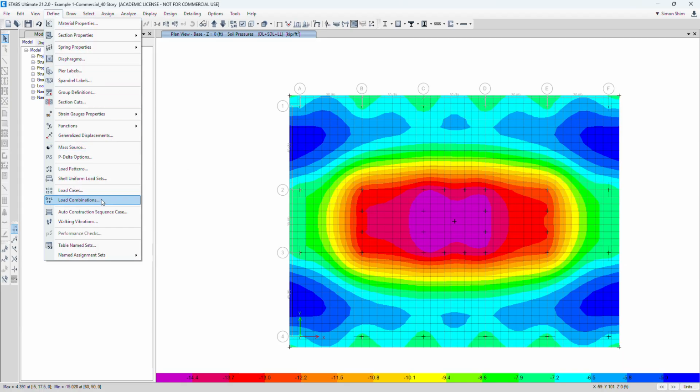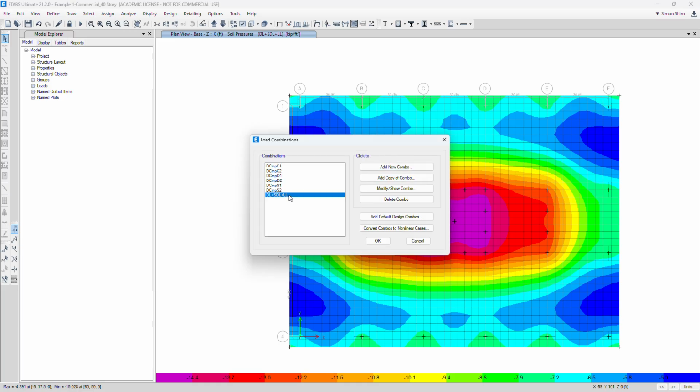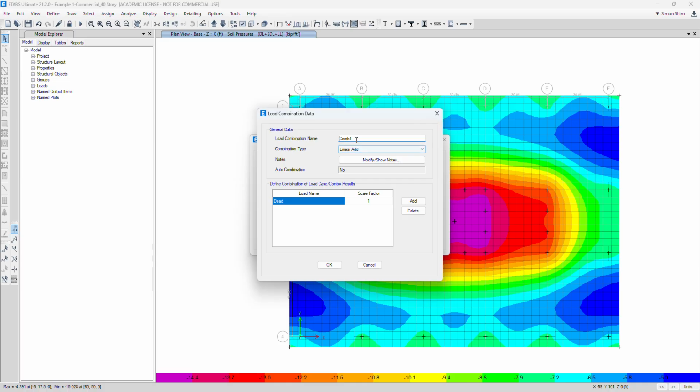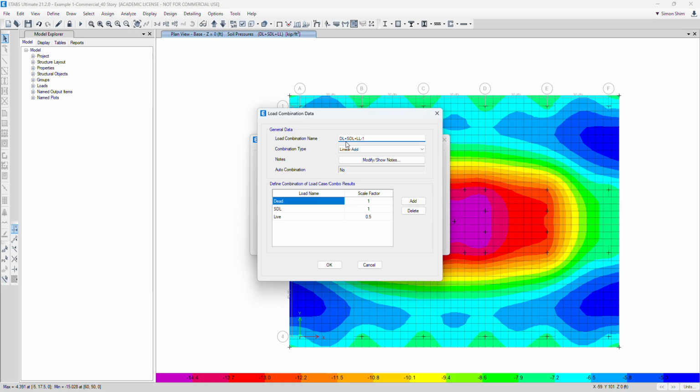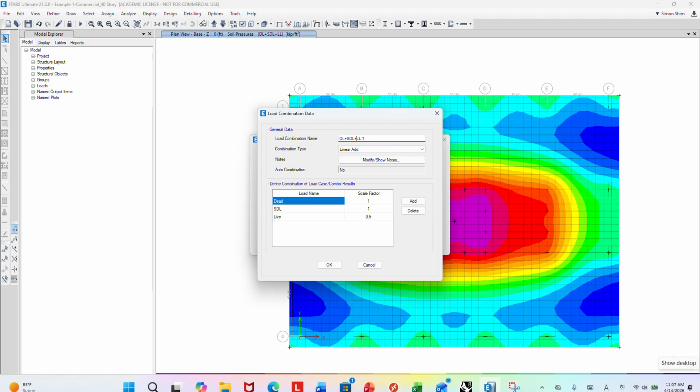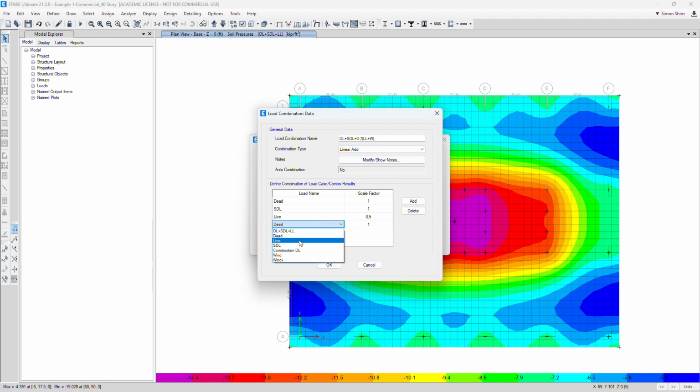Let's say lateral effect. So we're going to create another load combination engaging the wind together with gravity. Currently, ASCE 7, we typically use wind X. So I'm going to add wind, with 0.75 since it's the live load reduction time 0.75.